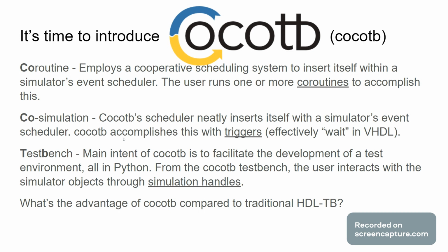Of course, cocotb is intended for making test benches. The idea is that you want to test your design in Python. The one cocotb component that I attach to the test bench is simulation handles. Simulation handles are just the references in Python that allow you to access the corresponding simulator objects. More about that as we continue on in the presentation.